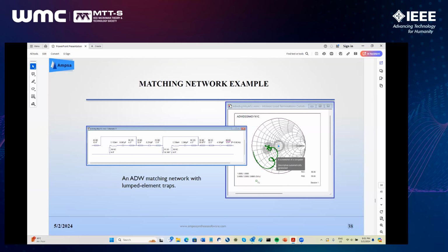So where it's controllable, you can see that it's best to make a class B. So there's always the story about we need all these continuous modes because we cannot do wideband specific class. Well, this is a wideband class B, sort of. You typically, yeah, I'll show you a bit later another one, but effectively, this was done by using traps.